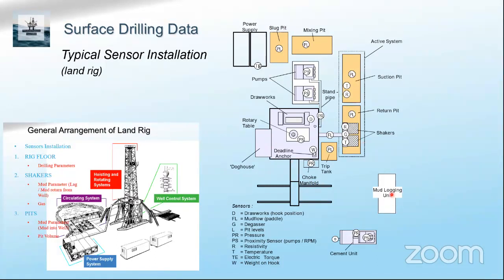So the guys will be running it, whether onshore or offshore, depending on the rig. In onshore, it is close to the shale shaker area. Why? Because all the sample cuttings come from the flow line to the shale shaker, and then all the cuttings are dropped here. Some tray will be put here, the sample plate. That is where the sample catcher collects it. The rest of the mud will be filtered and go back to the system again.